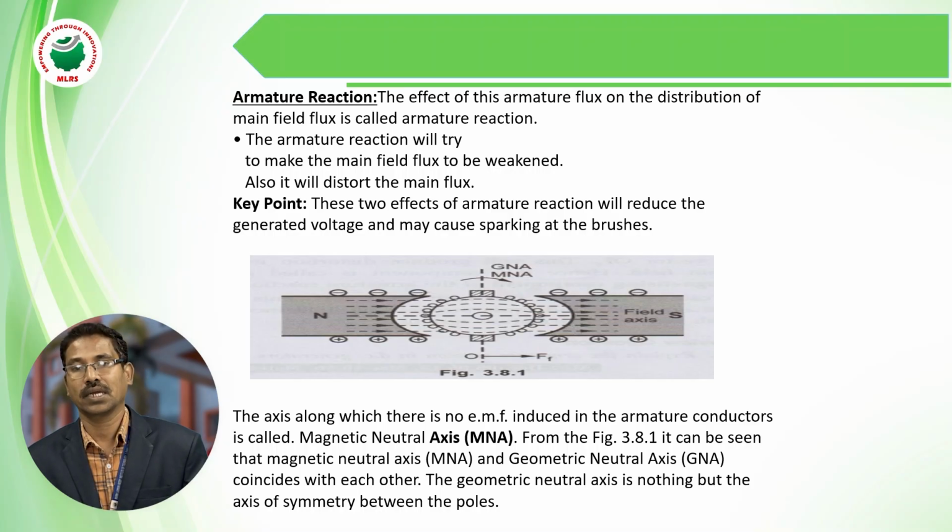So because of armature reaction, there is a reduction in the main generated EMF, and at the same time there is a sparking problem, or commutation problem.